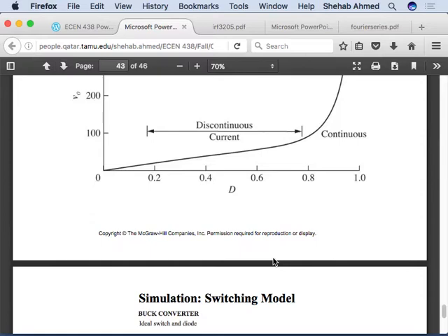And you're putting in what? 12 volt or whatever your power supply. Look at your adapter. It will probably be 12 volt or 9 volts or whatever. So you will have a few buck converters in the power supply, bringing down the voltage from 10 volts or 12 volts all the way down to 1.3 volts. Right? So you bring it down to 1.3 volt, but you have to make sure that you're controlling it such that the voltage regulation is very tight.